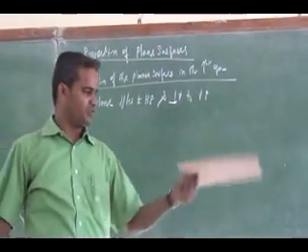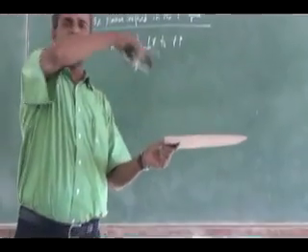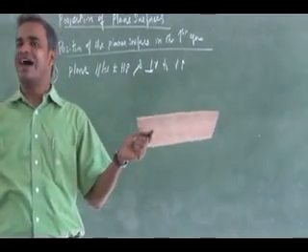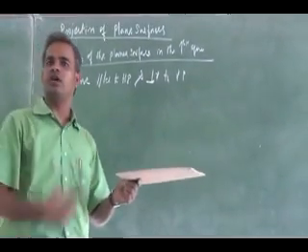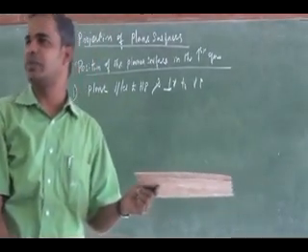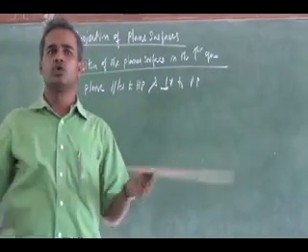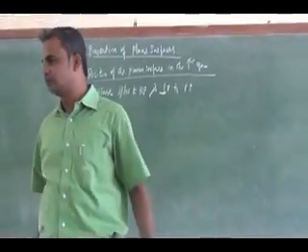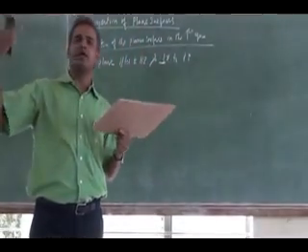So you see here, in this orientation I will obtain the true shape of the plane, a square, as the true shape on the top view. Wherever it is parallel, I will obtain the true shape, similar to a straight line. A straight line, if it is parallel to any one of the reference planes, on that plane I will obtain the true length. Similarly, on whichever reference plane it is parallel, on that plane I will obtain the true shape of the plane. So for plane problems you have to proceed by drawing the true shape of the plane first of all. Whatever the orientation, you will first try to draw the true shape, and from there you will proceed.